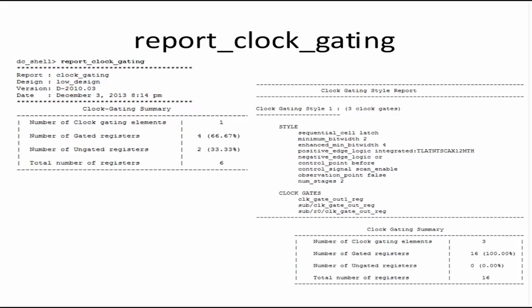When you code, you won't even know it, and it will be a shift register with an enable pin, which controls the feedback. So this is why clock gating is becoming so popular. It gives so much gain in terms of power saving, and the area increases not that much.